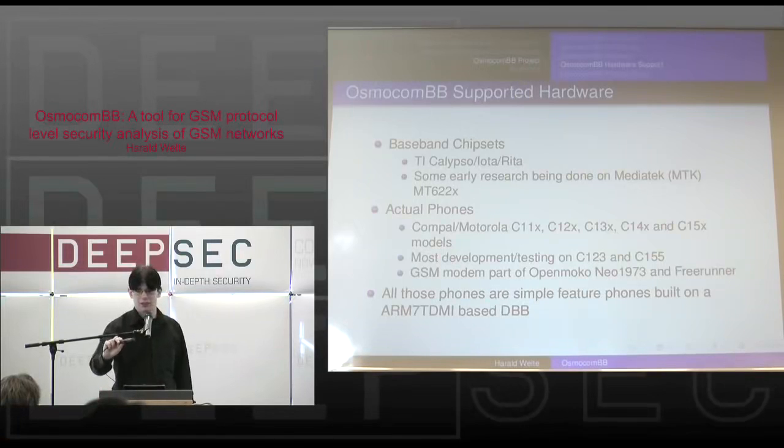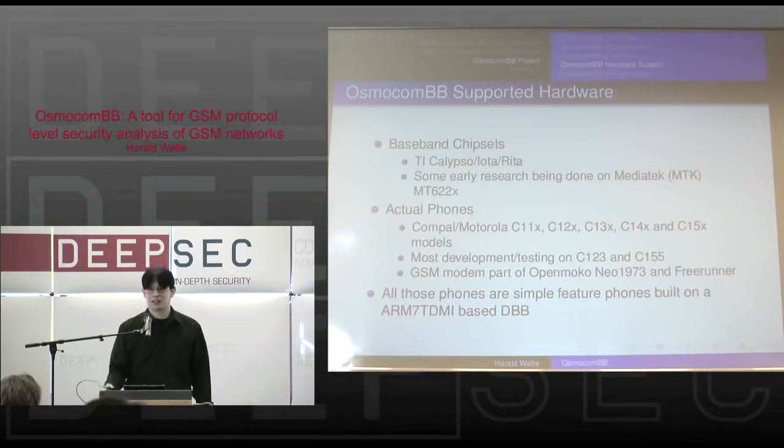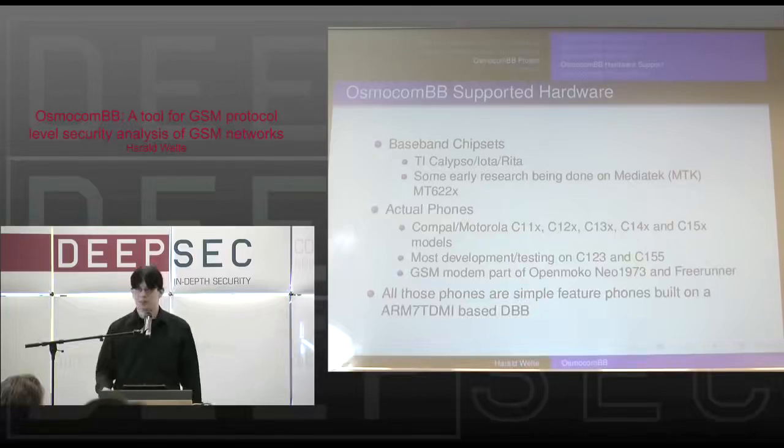It's a very, very small, low-end phone. It doesn't even have any USB or serial connection. It just has an earphone jack, and we actually download the software through the earphone jack, since that's not only an analog audio interface, but also has a multiplexed serial port on it.